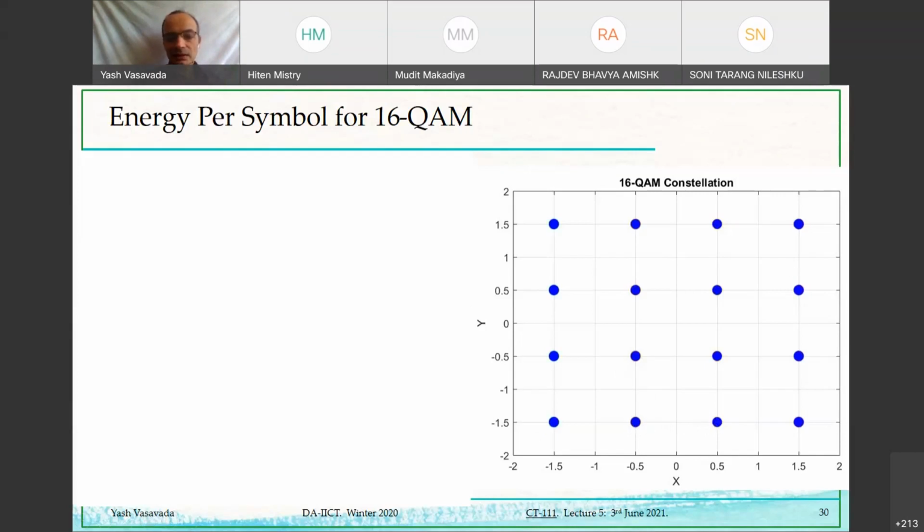But this other, maybe a little enthusiastic engineer who wants to minimize the energy per symbol in an average manner, he or she may say that, no, I will reduce the energy per symbol by putting the symbols not 1 unit apart, but only 1/10 of a unit apart. So it is as if I pack these 16 symbols in a much tinier region.